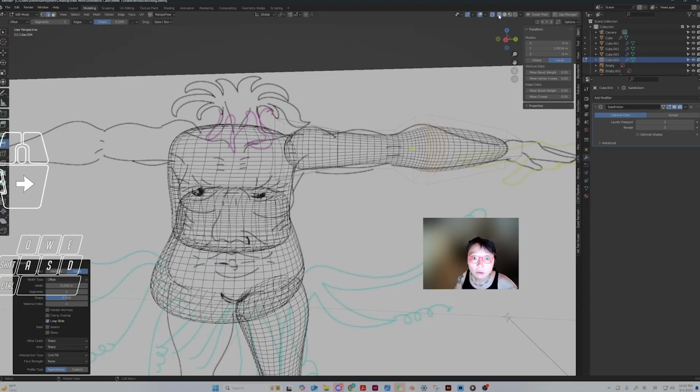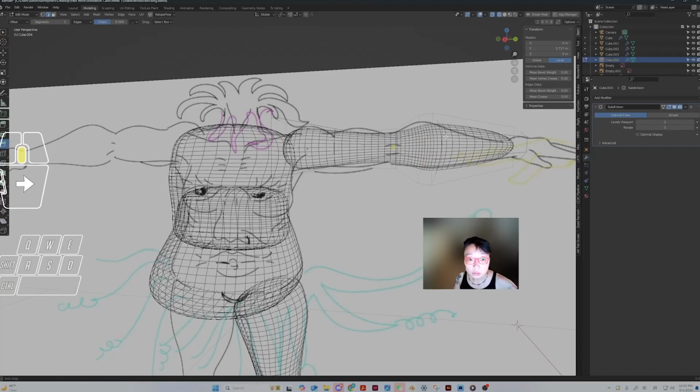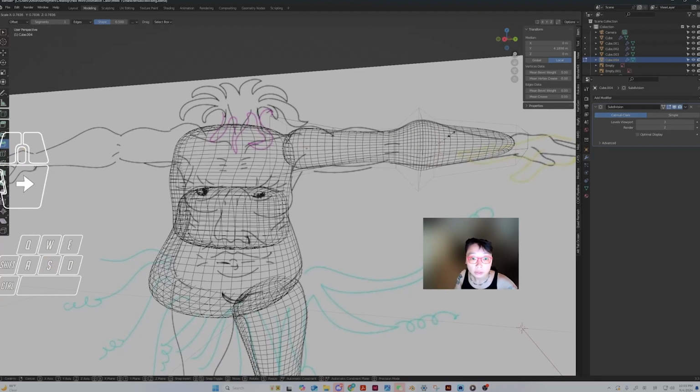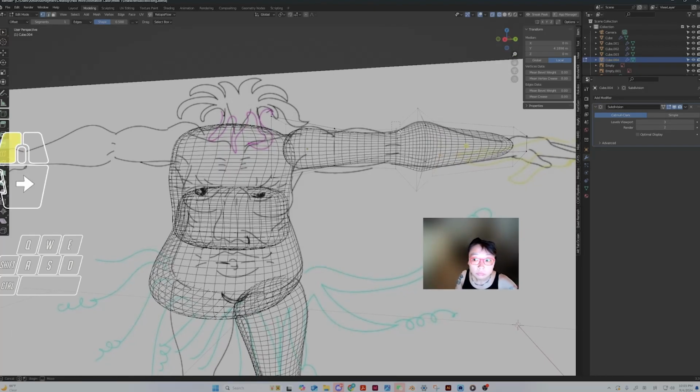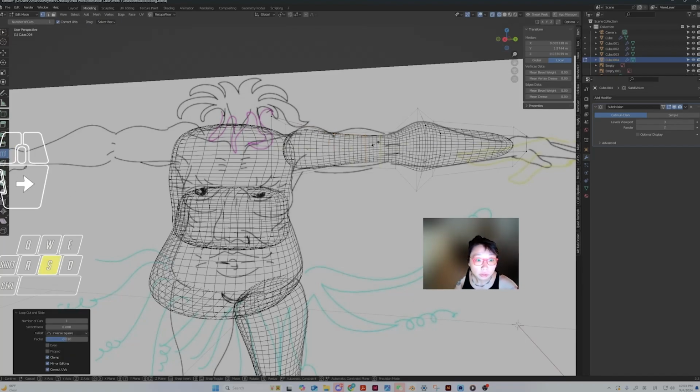Okay, so now go into vertex mode. Oh, actually, edge mode. Select this with Alt, right? Alt, and then bring this out. Select this edge. We will scale it in. See how there's additional muscle here? It just means that we need to add more loop cuts here. So one here, we scale it out. So another one here, move it, scale it out.